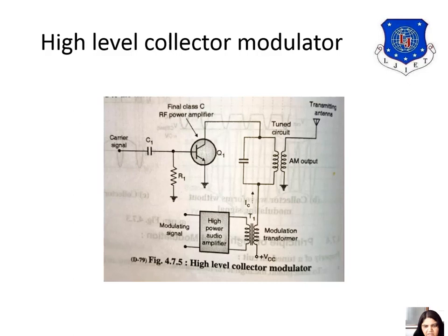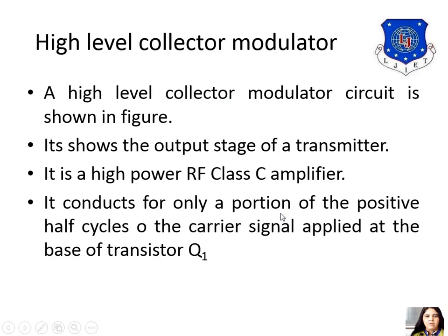Why? Because the value of the modulating signal EM is equal to VCC. When the modulating signal goes negative, it subtracts from VCC, and at the negative peak the subtraction is 0, and 0 voltage is applied to the transistor Q1, which produces 0 output.